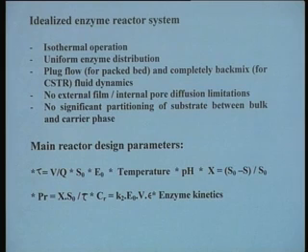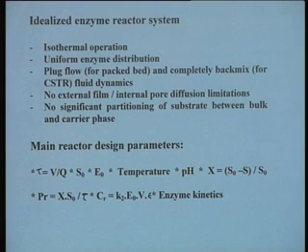Of course, in practice, even if you see the immobilized enzyme preparations themselves, there are reports that even in the immobilized enzyme preparation itself there is no uniform enzyme distribution practically, but for theoretical purposes we assume that the enzyme is distributed uniformly in the reactor, whether it is a plug flow reactor, a batch reactor, or a CSTR. The third condition is we are assuming either a plug flow behavior for packed bed or a completely back mix behavior for CSTR in terms of fluid dynamics.